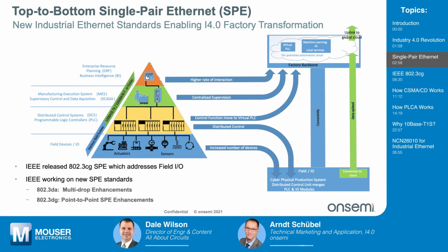But down at what today is called the field I/O devices, you pretty much have proprietary or legacy bus systems that connect your actuators and sensors to the actual distributed control systems or the programmable logic controllers. As you go down the pyramid, you also see that the number of wired connections down towards the field devices becomes more and more.